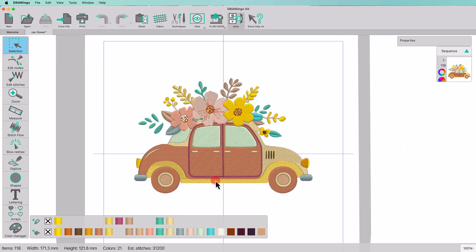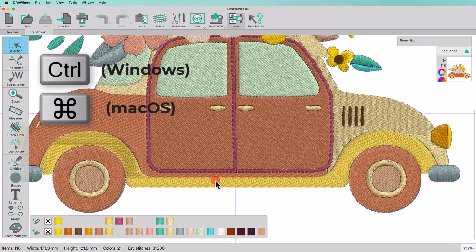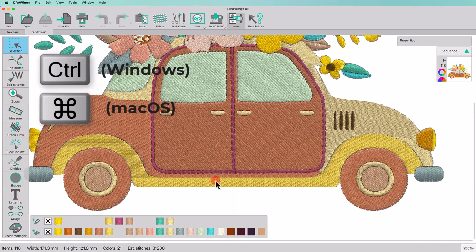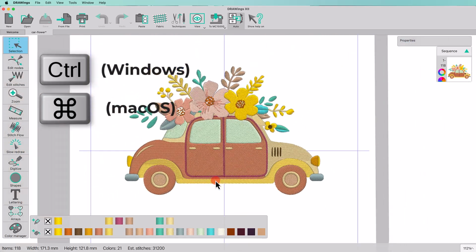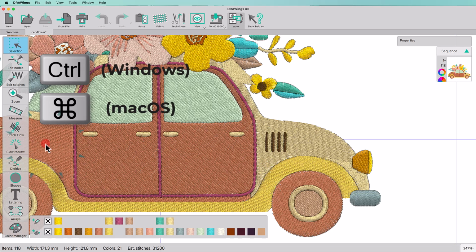In case you want to zoom in and zoom out using the mouse wheel, you need to hold the Ctrl key down while moving the wheel so the wheel temporarily switches to zoom mode. If you scroll in, then you zoom in. If you scroll away, then you zoom out. Notice that the point where your mouse cursor is the zoom point.